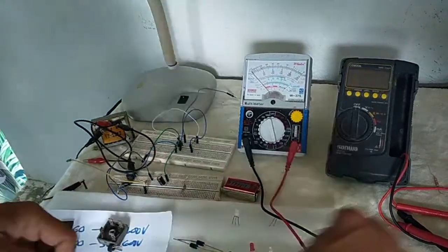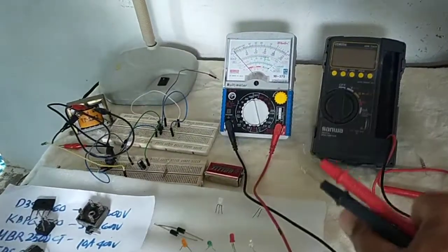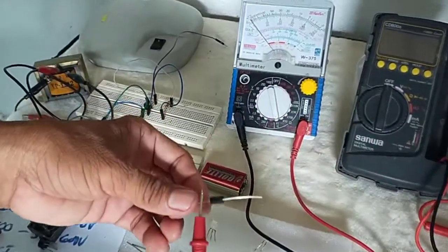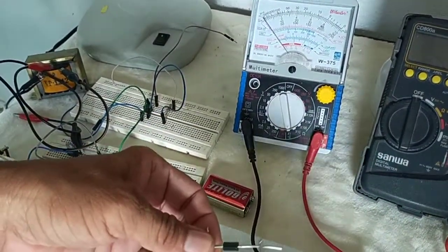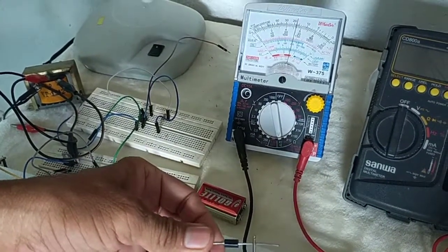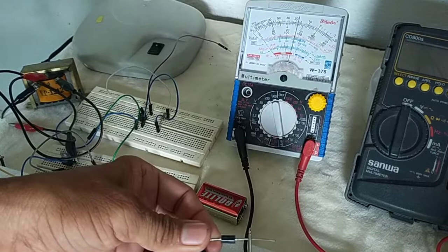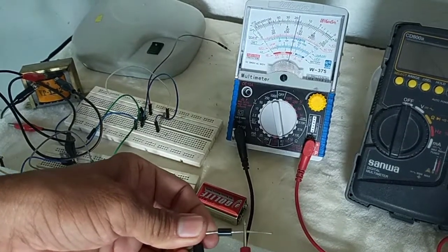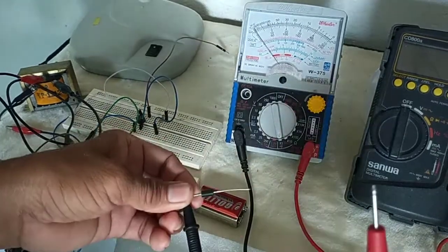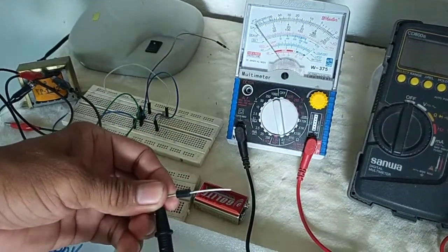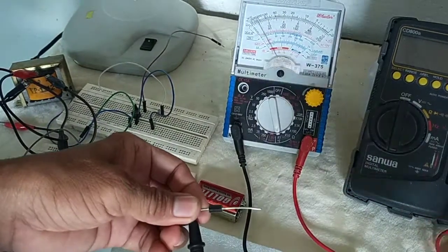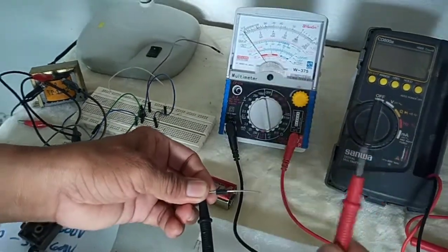Okay, let us now come to the measurement. At first, let us measure the normal measurement of this diode. The purpose of this is to locate the electrodes, the anode and the cathode. Focus on the forward bias. When the pointer deflects, that indicates that there is a current flow, and it is forward bias. This test rod is negative, and this is now the cathode.